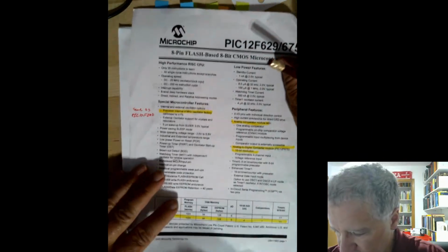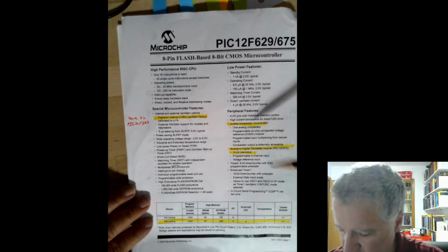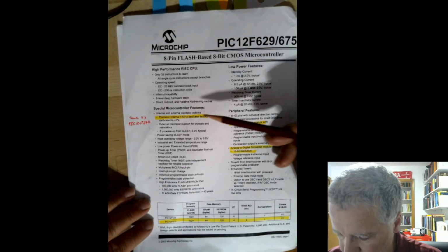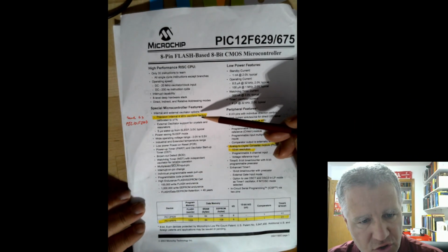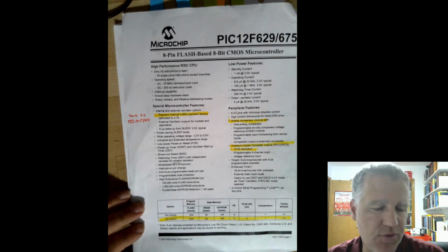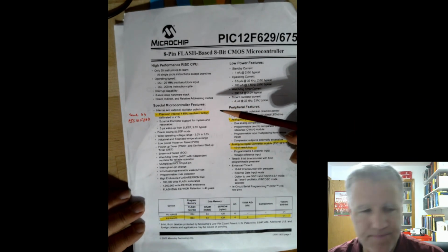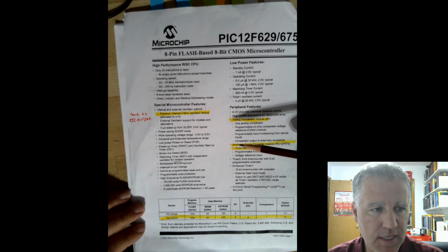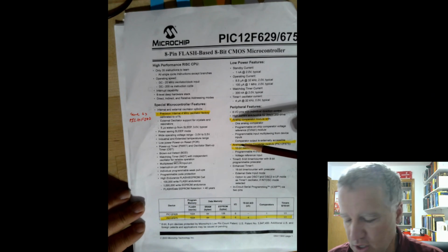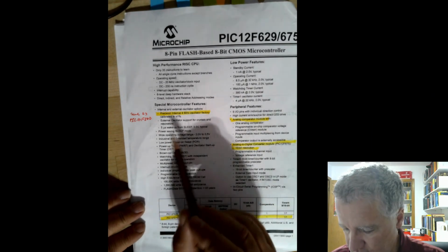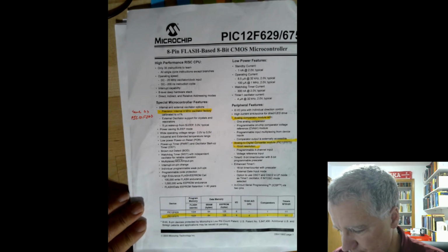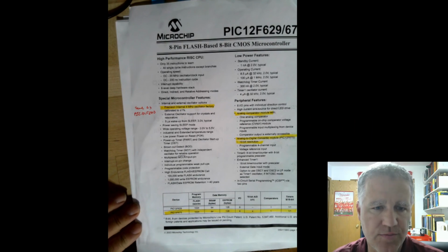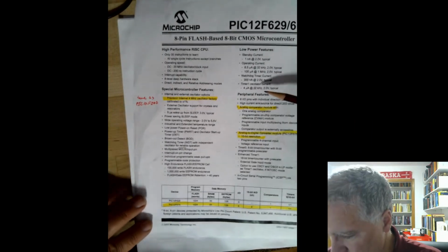And I feel like I use it a lot, so I think it's worth printing off. All right, let's just start with a basic outline. Some of the stuff I mentioned on the board there, but some new stuff here. So it has an internal clock, and we will just use the internal clock. Good exercise, I suppose, to make circuits with an external clock, but we will use the internal clock. 4 megahertz, which is the same as the PIC10F200. So a lot of our delay sequences will be the same, so that's kind of handy.